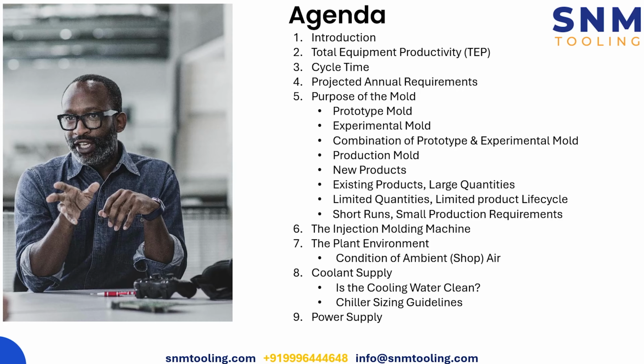And then we'll dive deep into the injection molding machine, how exactly it affects the design of the mold, basically the construction and the dimensions or the tie rod distances, those will come into play. Thirdly, we would study the plant environment. What exactly are the requirements from the plant perspective, given the compressed air, and so forth. Then we will discuss the coolant supply.